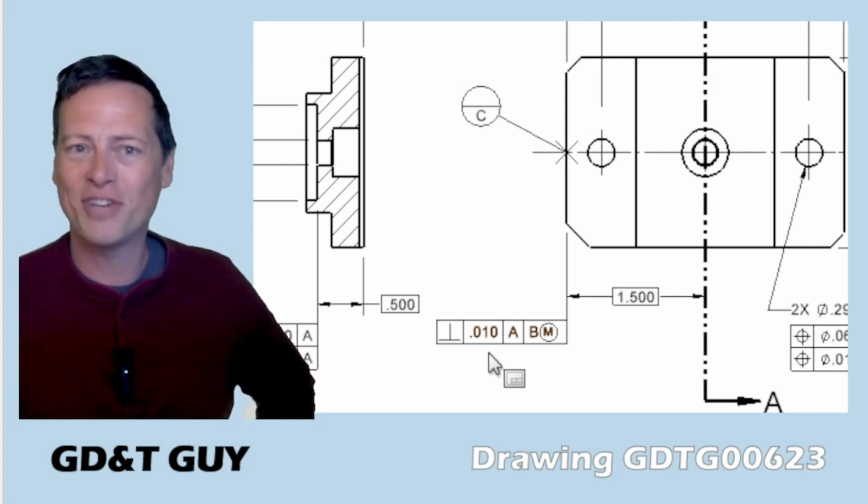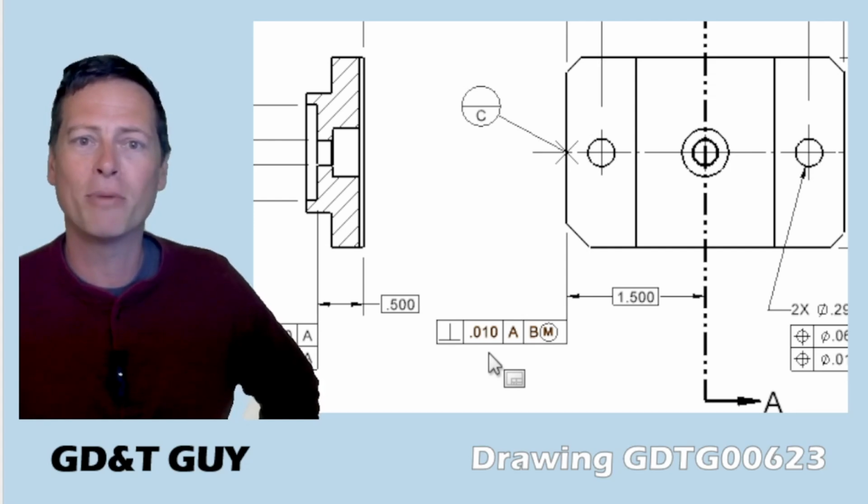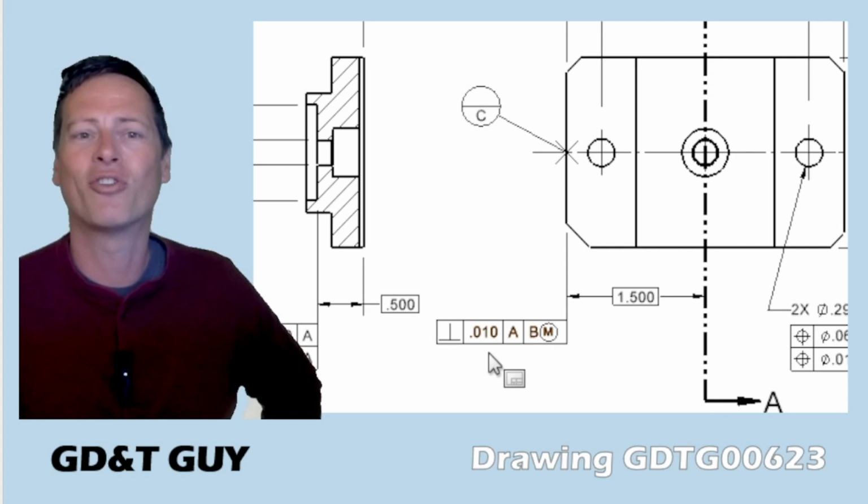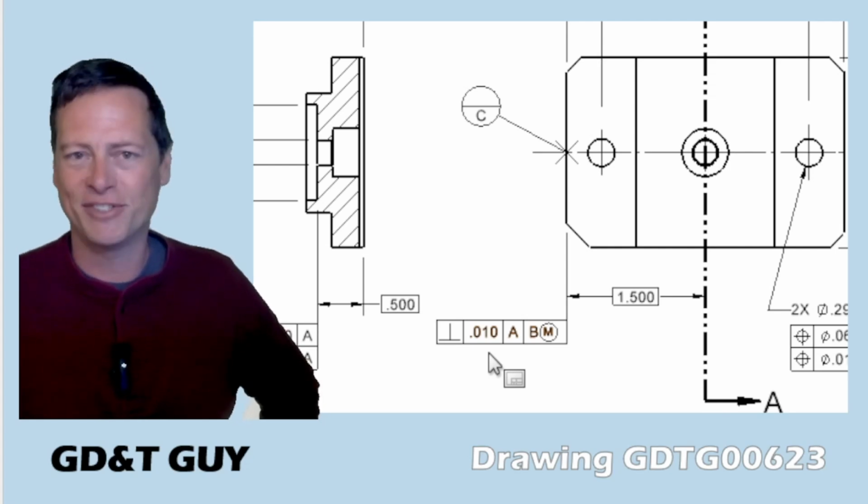Well, we're a little off topic, but seeing those two changes together makes me think we can back off the perpendicularity from 4 thousandths to 10 thousandths, or even more. Great. This is really just so you can see some options.